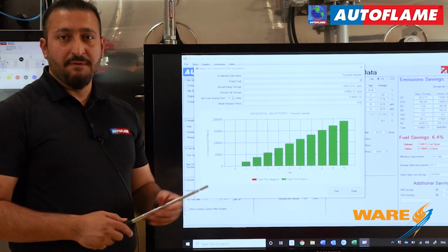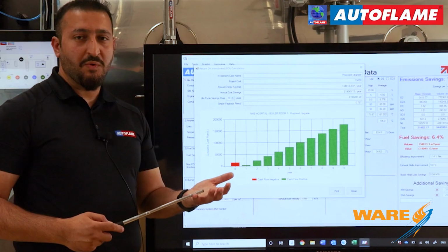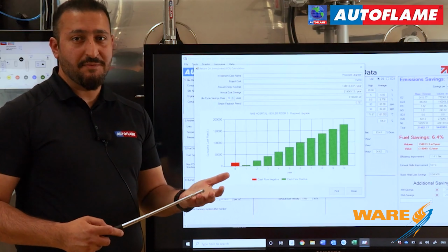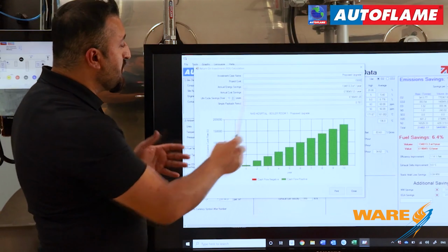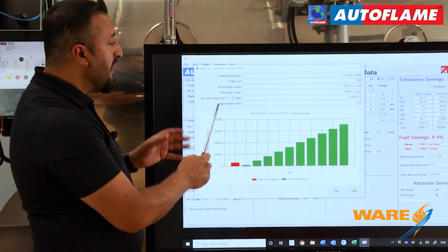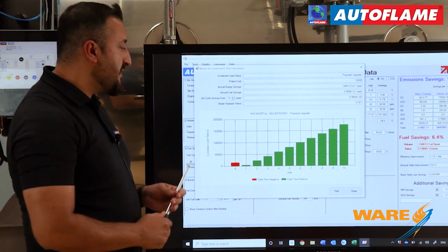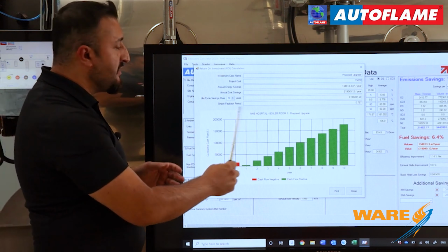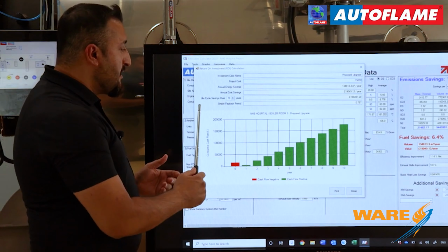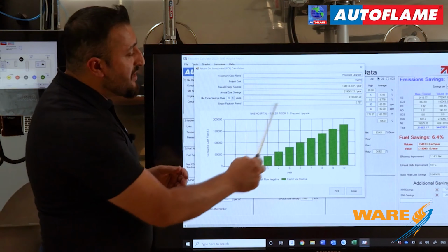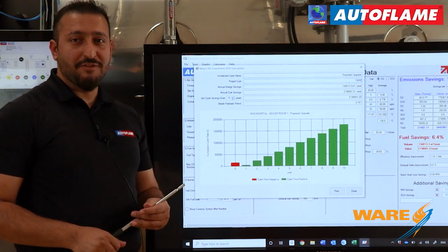But for this particular example, let's say we're using £15,000 as the cost of labor, equipment, installation, and final commissioning. Once we put in the project cost, now it's taken into account our annual energy savings and also the cost savings. This is life cycle savings of over 10 years period. And based on the information we put in, simple payback period is about 0.8 year.